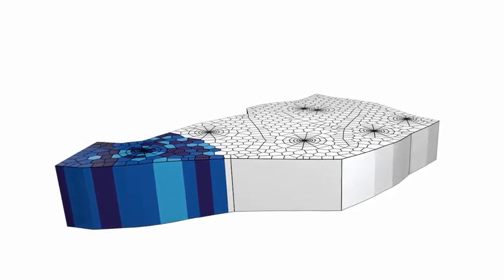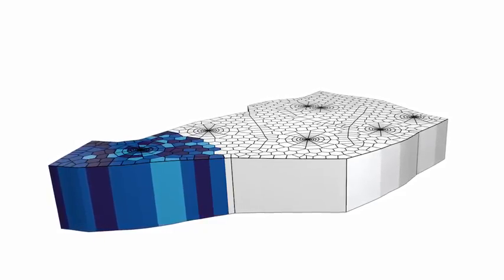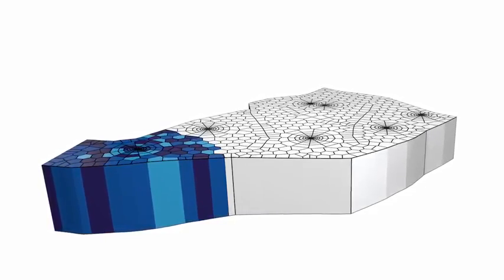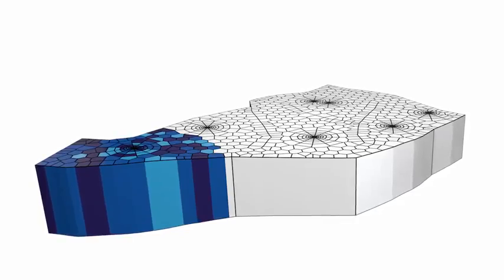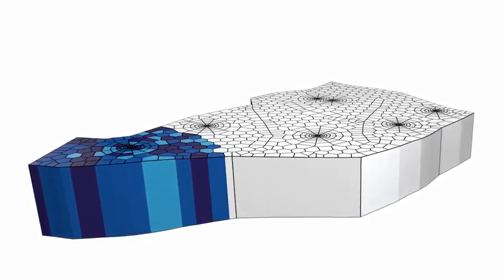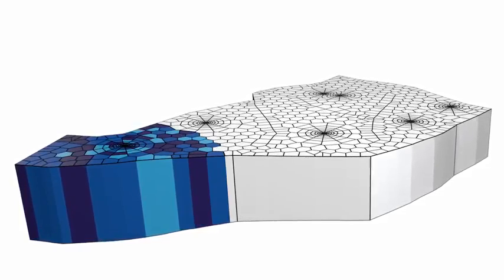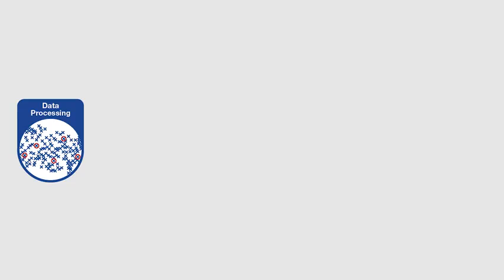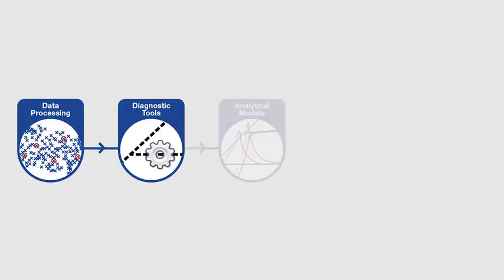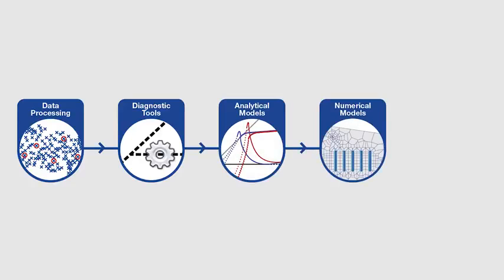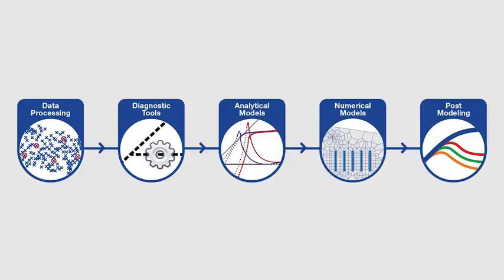from the application. The high-frequency, high-resolution pressure response, mainly from shut-ins, can be used to provide wellbore, near wellbore, and in the case of extended buildup or deconvolution analysis, boundary and hence reserves information. The diagnostic plot of choice is the log-log plot, where the pressure and the Bourdet derivative are matched with the built-in analytical library models and rapid build numerical models.